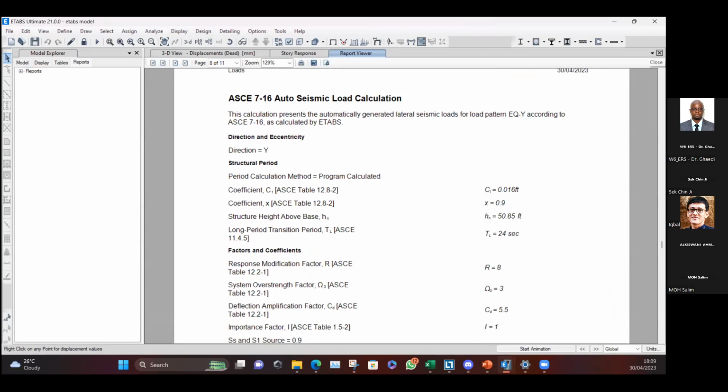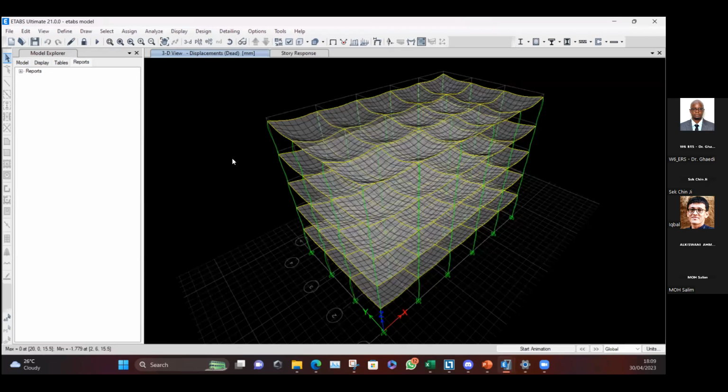And yeah, that's it. Definitely we need to check the values obtained from the software with our hand calculation. Okay, so at least maybe one time or two times, you need to do that. Actually, you need to understand the accuracy of the software calculation and result. Okay, so we should not blindly use the software. So this is the thing. That's why it is strongly recommended, as I told you, before using the software, test the software by comparing the result between your hand calculation and the result obtained from the software. Okay, maybe for one time, a second time. So if you find everything is fine, then you can go ahead.